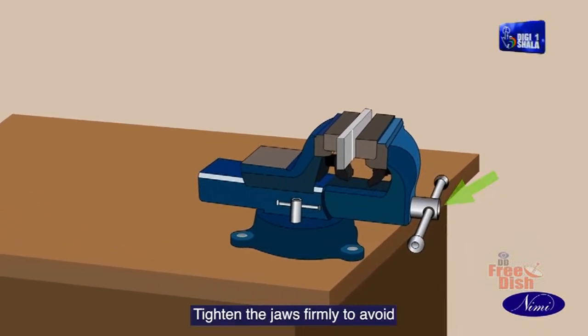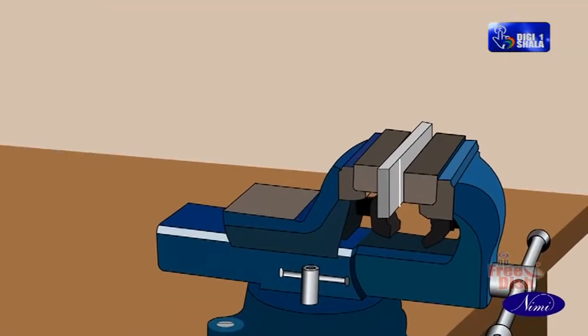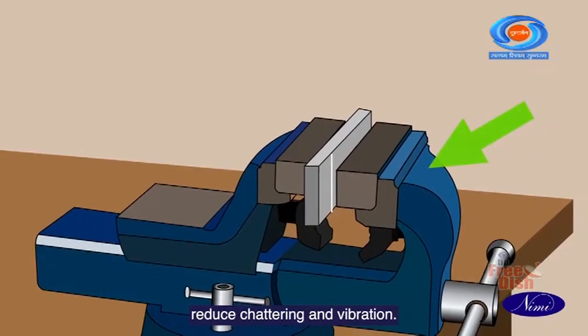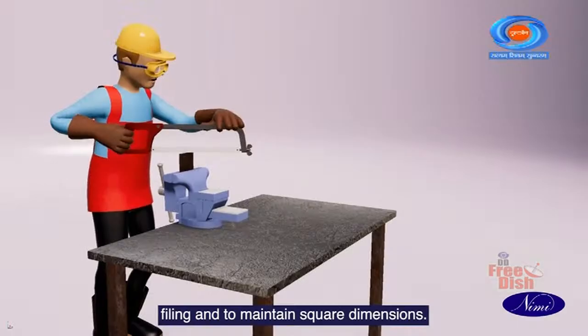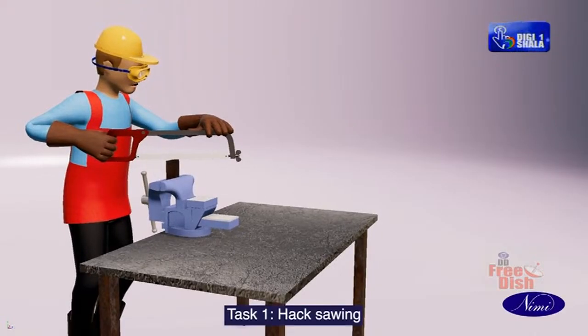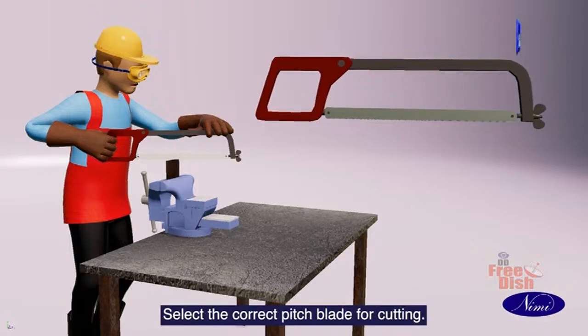Tighten the jaws firmly to avoid tilting and shifting of the job. Clamping needs improvement to reduce chattering and vibration. Now let us see how to perform filing and to maintain square dimensions. Task 1. Hacksawing. Select the correct pitch blade for cutting.